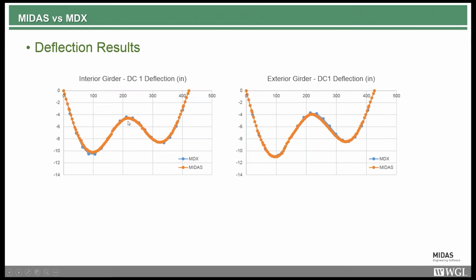Okay. So the first question is, the model method is girder using beam element and deck using plate element. Then the composite beam element is used. I wonder if the deck stiffness is counted twice in the model, once in the composite beam element, then in the plate element. Yeah, that's the question.